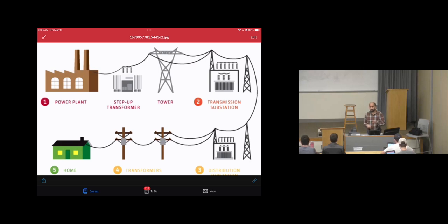Decrease. So if you increase the voltage, the current will decrease. This yields lower losses. Therefore, the best way to get lower losses is to use high voltages. That's why we have high voltages nowadays. If we make high voltages, the range can be up to 132 kilovolts. It can be 230, 400 kilovolts, 500 kilovolts, different ranges. These are very large values.